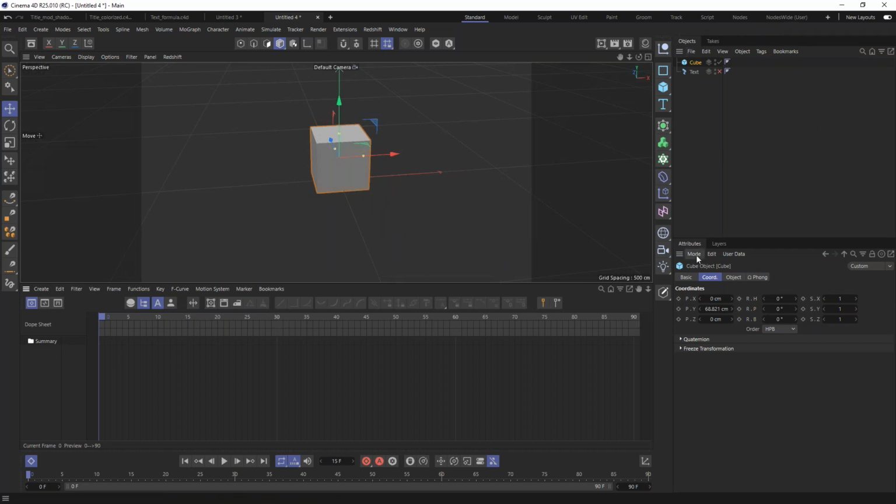Okay, so here I want to create keyframes, and this is going to be the end animation. Let's go to the 20th frame, and I'm going to create an animation on Y. I want to move it up, so I create the keyframe. I want to animate on this axis. Let's go back to 0 and create a keyframe. Why not this axis too, create a keyframe, and I want to animate the scale, so create a keyframe. All right, so everything has been recorded here.